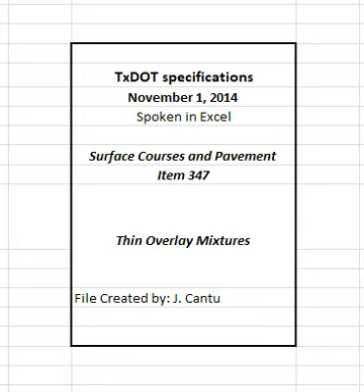4.4.2.2 Engineer's responsibilities. 4.4.2.2.1 Gyratory compactor. For mixtures designed in accordance with Tex-204-F, Part I, the engineer will use a department TGC, calibrated in accordance with Tex-914-K, to mold samples for trial batch and production testing. The engineer will make the department TGC and the department field laboratory available to the contractor for molding verification samples, if requested by the contractor.